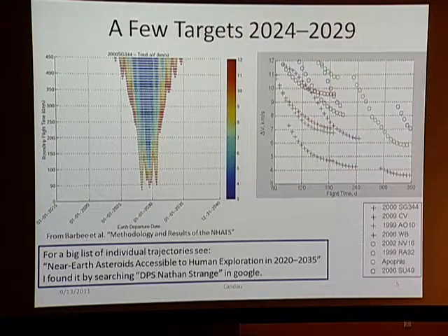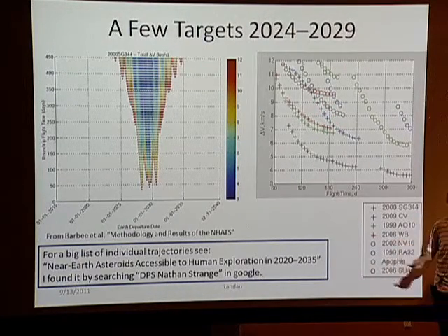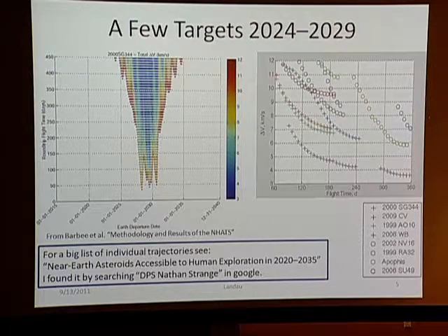So if the life support people say, okay, no, there's no way in hell that we can keep somebody alive for 150 days, then you say, okay, well, if we're able to go a lot longer, we're able to do this, if we're able to push down, then it costs this much. And part of the idea is to look at these curves and try to find the knee in the curves. When do these things start to take a turn for the worse or the better? So if there's a trade in the flight time, say, with technology that we have now, or the Orion crew capsule, we can keep people alive for 150 days. But as you go down in delta V, the propellant mass goes down, but the habitat mass might go up. And when you include the entire system, you can end up with an optimum in terms of your launch mass or your cost or something like that. So this just gives an idea of how these things play into each other.